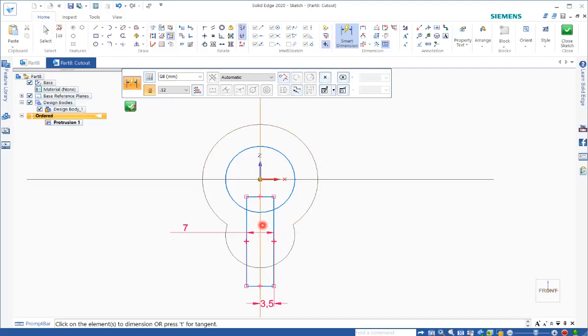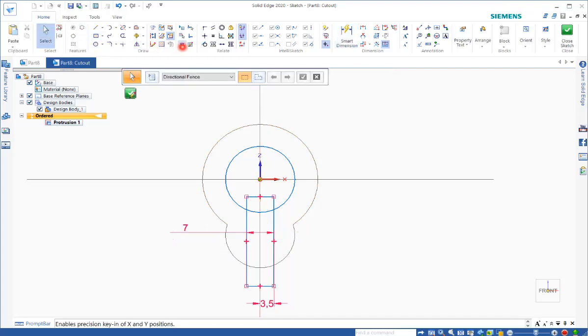Obviously it's not the same as the drawing, you should actually follow the drawing. Now we use select, then we select trim. We can remove the lines we don't need. Okay, so the original shape will be trimmed by the one we just drew.